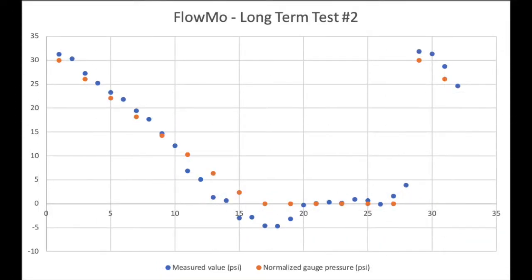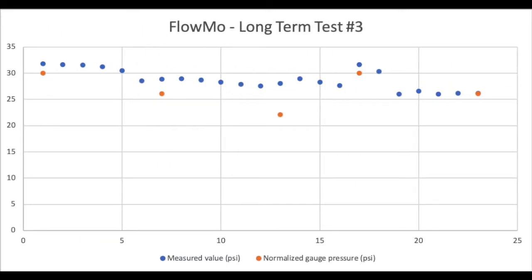The second test was similar, but once the pressure in the rig had reached 0 psi, it was pumped back up to 30 to confirm that the sensor can also detect large changes. The third test was an oscillating test where the pressure was allowed to briefly reduce from 30 before it was pumped back to 30 to test the short-term response of the sensor.